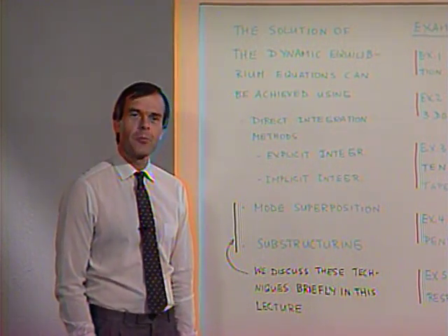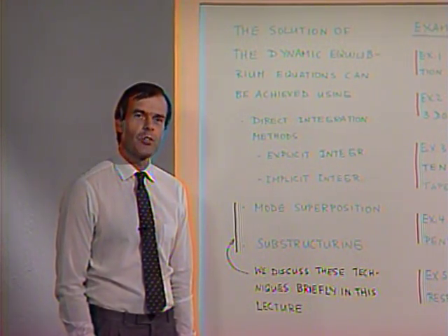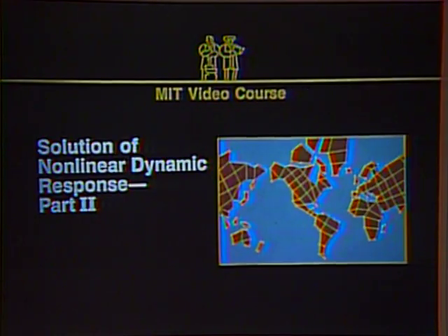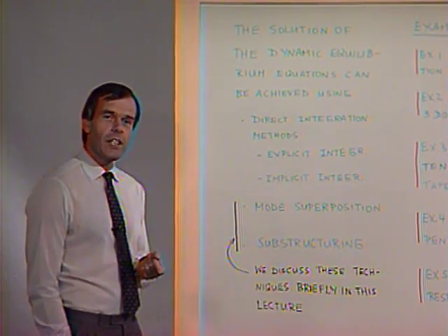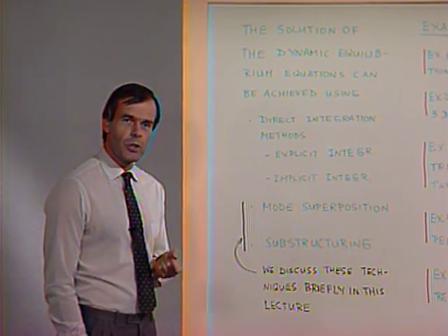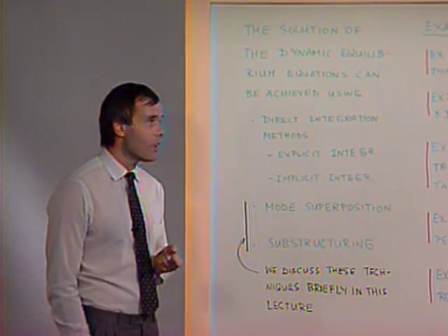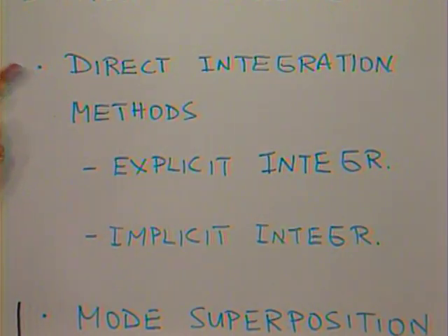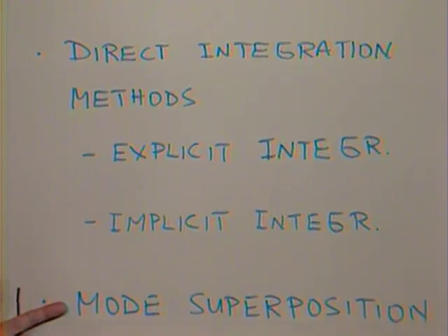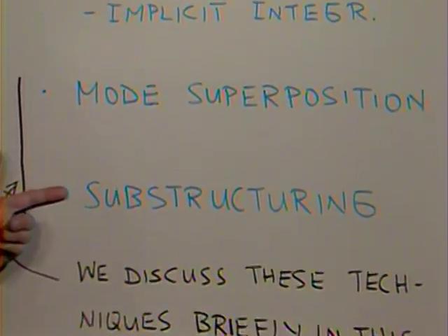Ladies and gentlemen, welcome to this lecture on nonlinear finite element analysis of solids and structures. In this lecture, I'd like to continue with our discussion of the methods of solution for the finite element equations that we are encountering in nonlinear dynamic analysis. In the previous lecture, I pointed out that the techniques used for the solution of the finite element equations in nonlinear dynamic analysis can be classified as direct integration techniques, methods of mode superposition, and substructuring.